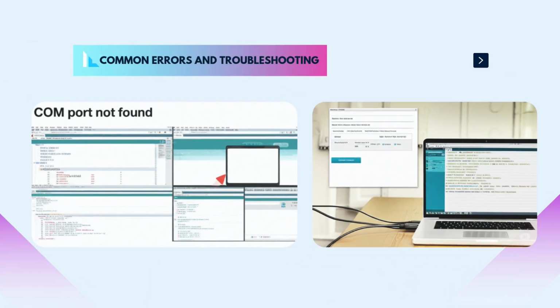Sometimes you'll run into upload issues. Check that the board is connected properly, the correct port is selected, and no other application is using the COM port. Restarting the IDE often helps too.